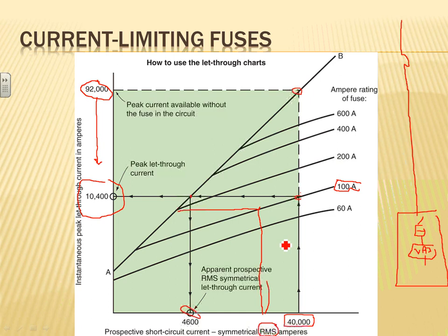So the coward's way out is to do something else. Like on large facilities, you put in a one-to-one transformer and knock your fault current down by at least half, using the impedance of the transformer, and solve that.